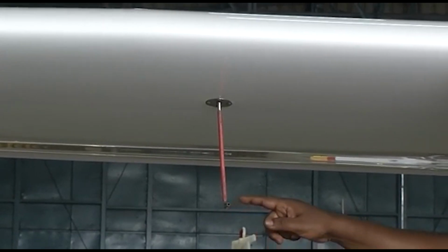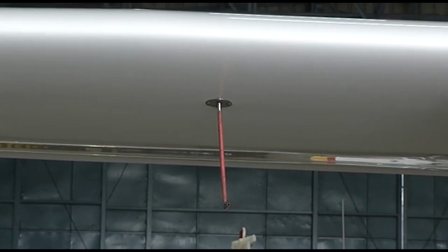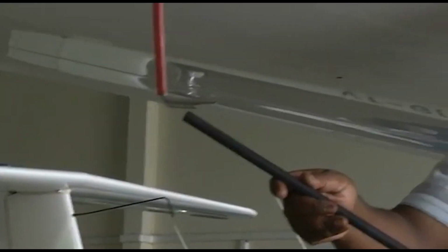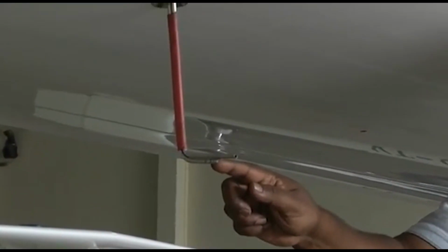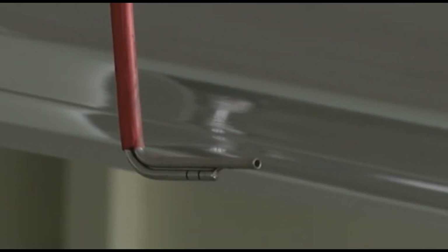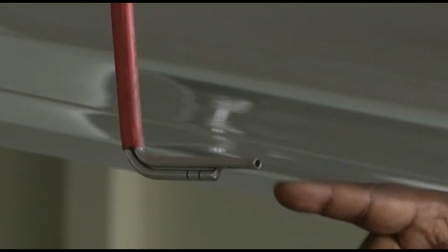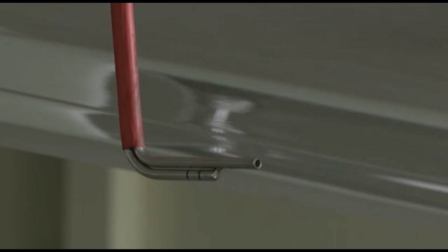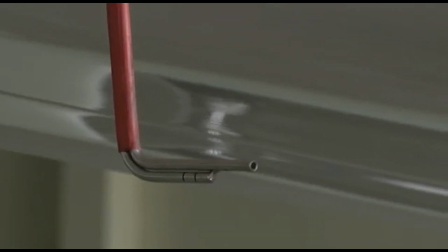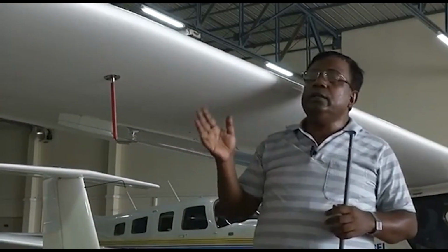Here all the air goes inside and total pressure goes to the airspeed indicator. You see the static points here. From here the static pressure input goes to the airspeed indicator, and you know there is a diaphragm, and the differential of total pressure, which is inletted through this point, and the static pressure from here goes to a diaphragm, and because of the difference in pressure the diaphragm will contract and do like this. Accordingly this motion is translated through a lever and you get the readings.